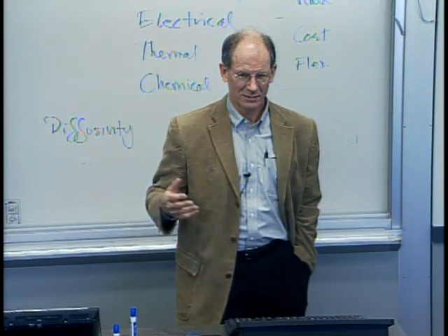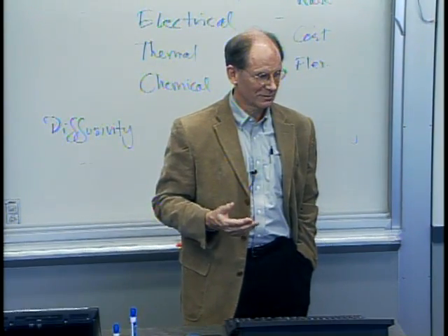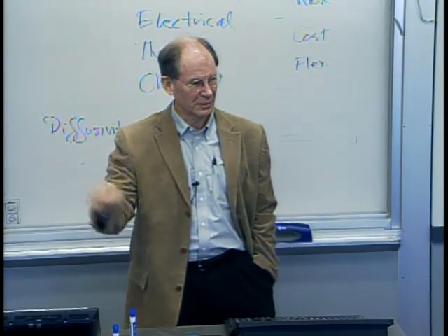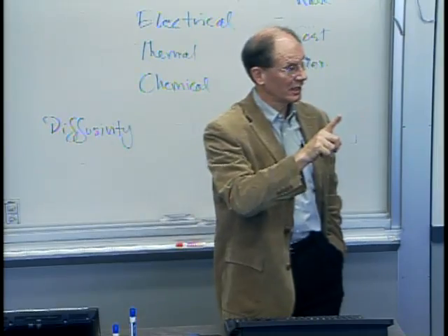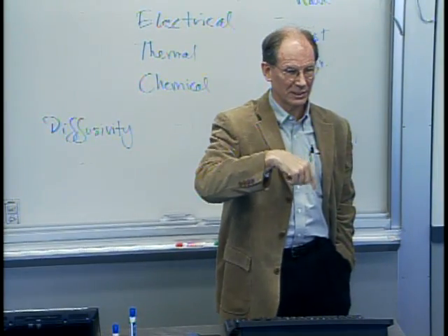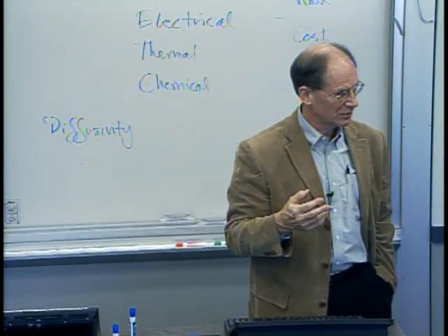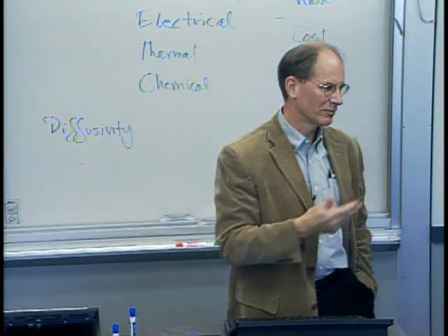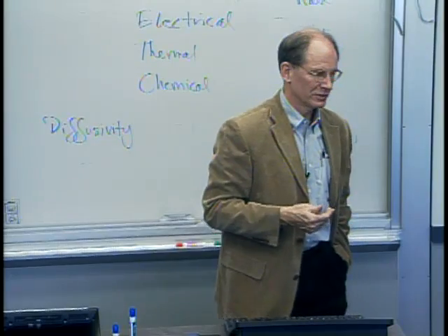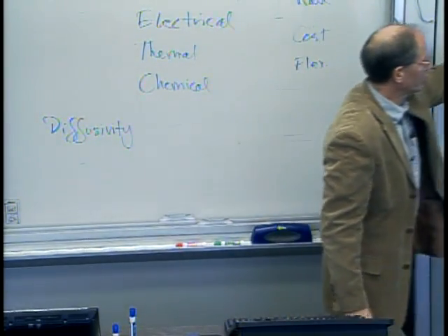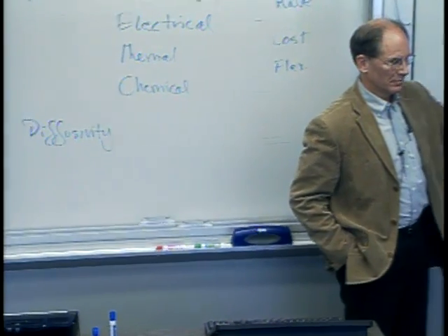Once I programmed your name in there, and then your name, and then your name, there's absolutely no overhead to me switching, because all I have to change is the trajectory of the tool. And nowadays with CNC control, that's a zero cost changeover. There's a minimal cost in creating the programs for simple things like that. So yeah, obviously something that is purely serial makes a big difference.